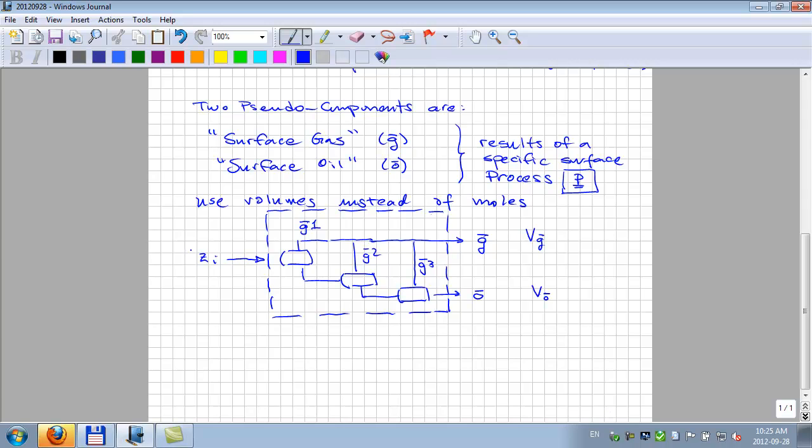Now this composition here that we've got, if we take that mixture and say that it is single phase, at a particular pressure and temperature in the reservoir, in the tubing, wherever you like, at the pipe just entering the process, it is still that mixture. But if it happens to be single phase, then it will have a volume, correct? At pressure and temperature. And that also comes into our black oil formulation.